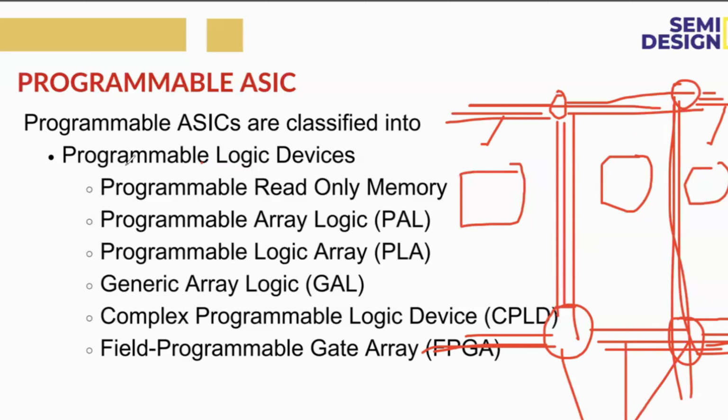If I want to make a connection from one logic block to another, first I need to send to this interconnect and the nearby switch, maybe upside or this. Then from the nearby switch to this switch and then this bus path, so that here I can connect with the next logic block.